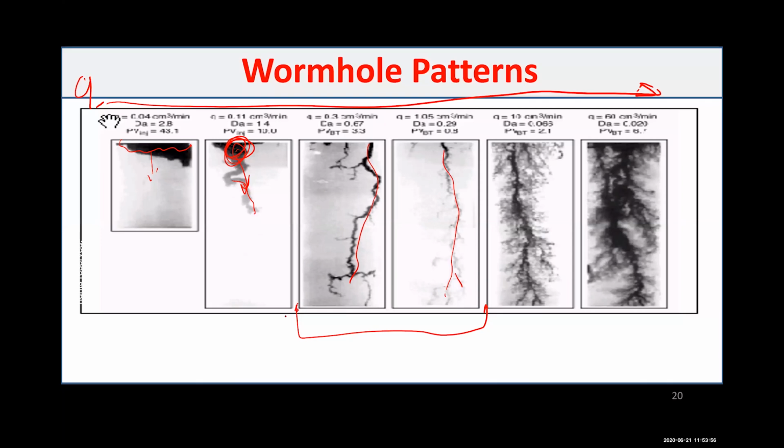That's why when we are designing for carbonate, we would like to pump as high as we can to be able to create this nice wormhole. At a lower rate, you will have the face dissolution and you will also have a well integrity issue, so you don't want to have this type of scenario. If your rate becomes extremely high, you will see what we call branching. You'll get a main wormhole, but away from it, you will have a lot of branching happening. But this is not happening so often. So a lot of the time we will recommend or design based on the optimum wormhole.